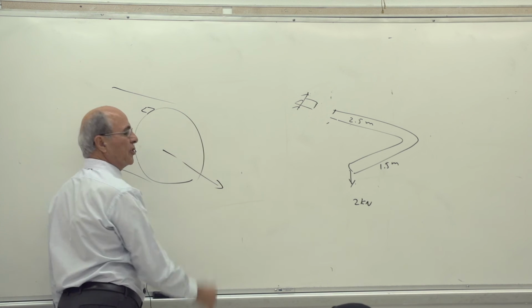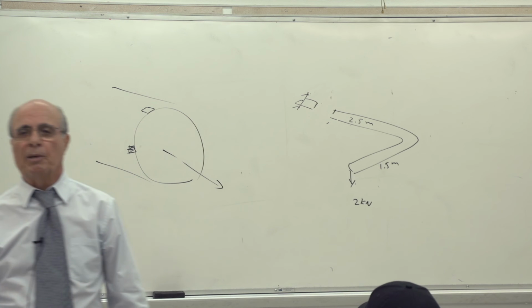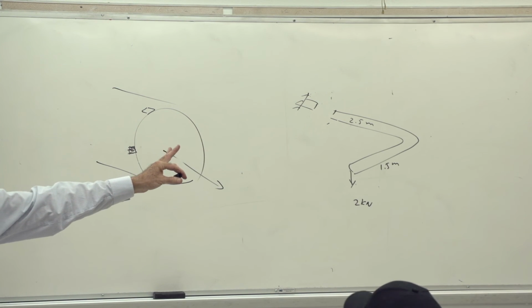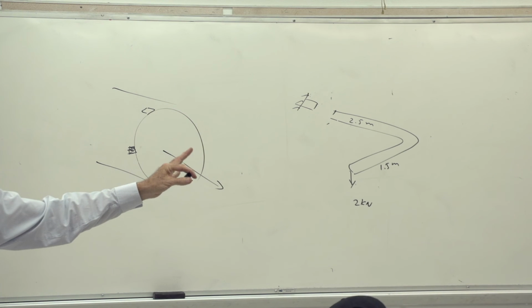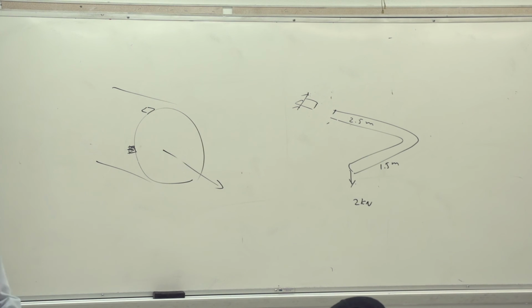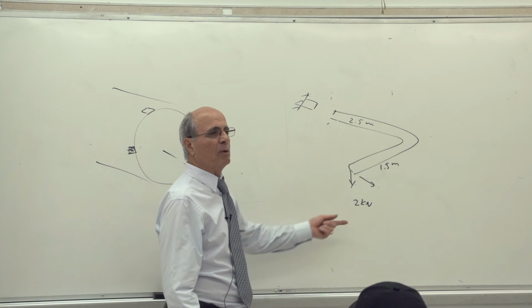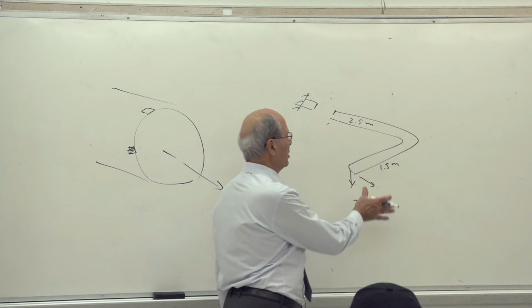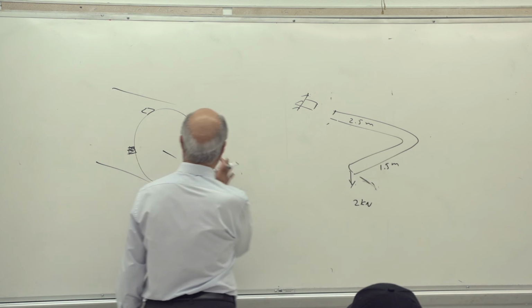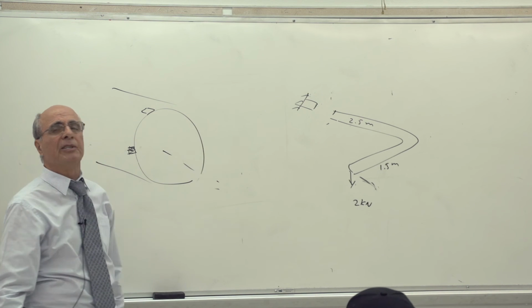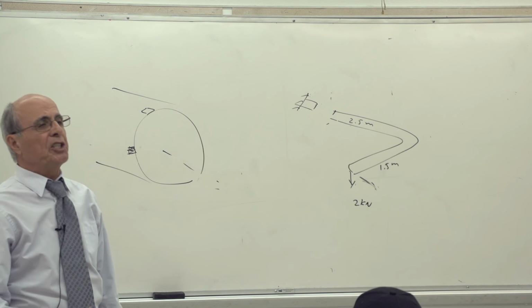Do we have an axial force here for this problem? This is a static problem. If you have a problem with statics, don't start this problem at all. Is there an axial load there? No, because if I wanted an axial load, I should have put a load here. Everybody knows that will be transferred into an axial load. Is that correct or not? So there is no P over A here creating stresses. Is that understood?